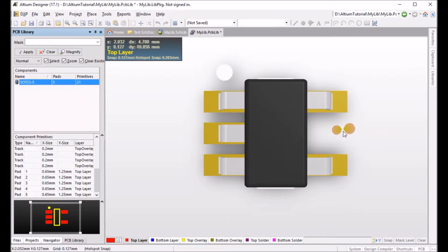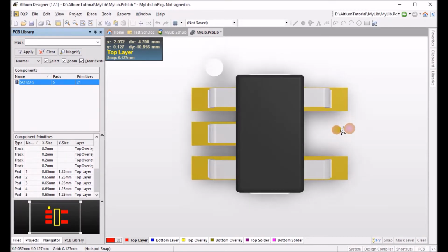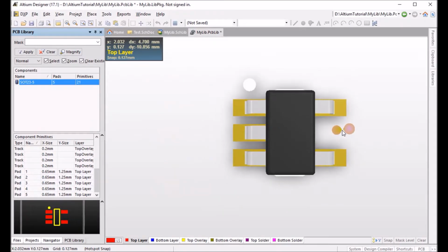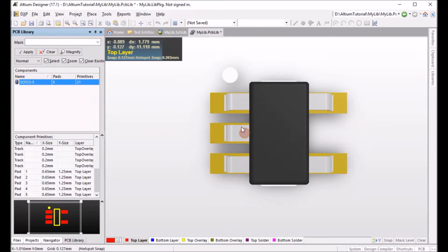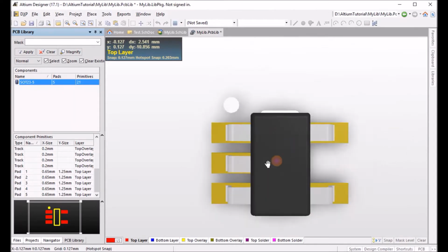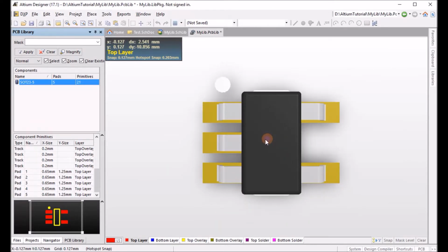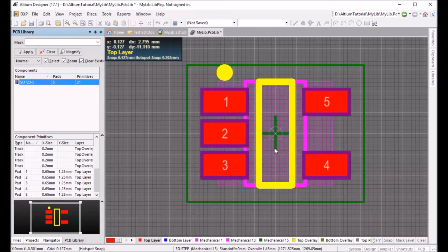Again, if you hold Ctrl and right click, you will zoom. If you hold Ctrl and scroll the wheel, you'll zoom again. And if you just want to move everything around, right click and just move the mouse. So basically, right click the mouse and hold for moving anything, and with the modifier keys like Shift, Ctrl, you just change the way the things move. They either rotate or zoom or they move. Now press button 2 to switch back to two-dimensional view.